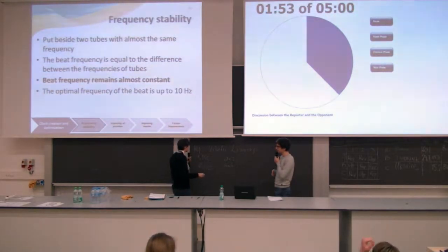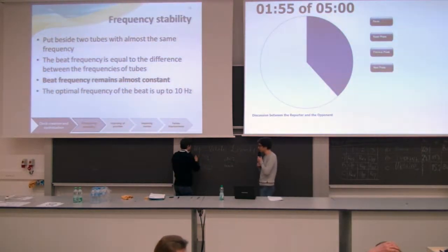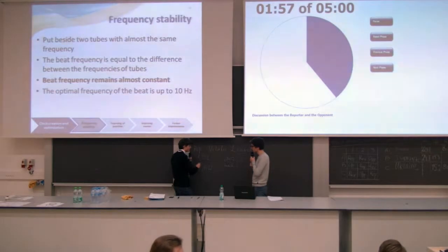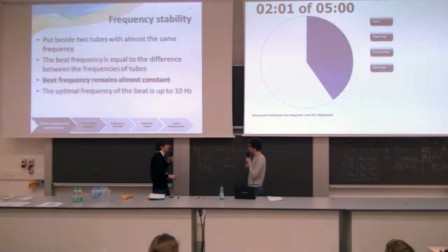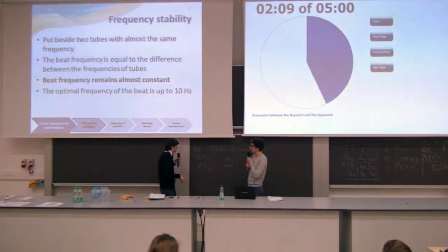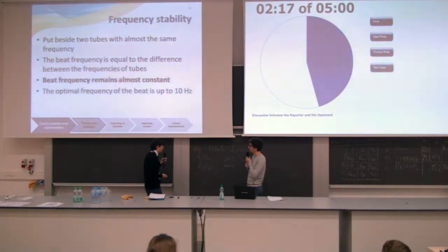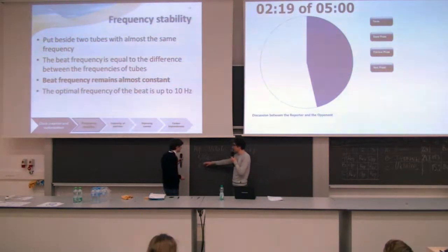I've proved experimentally that we have a much worse situation when using such a low frequency. I tried to make a block based on 1 Hz frequency, and it was not precise. I don't know why, but the frequency was really drifting, from 0.9 to 1.1 and so on. And when I had 10 Hz, it was okay. So we had a very precise clock, and you see that 15 minutes is okay. Is 10 Hz the frequency of your sound?